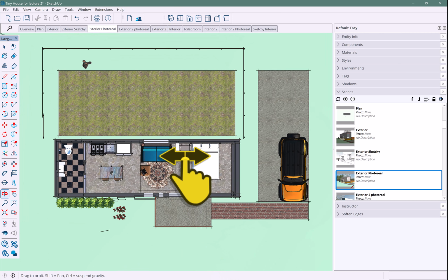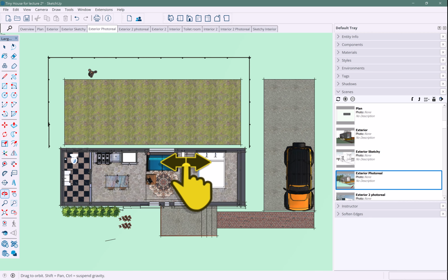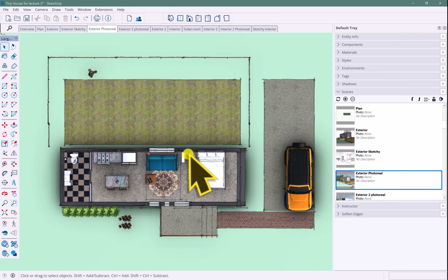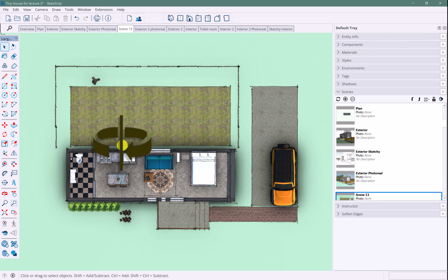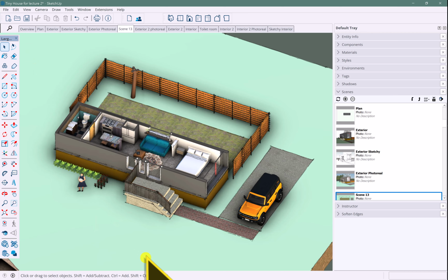So now, once we come into this view, once you flatten it, some of the ambient occlusion and other features aren't nearly as dramatic, but you can see that it makes a pretty decent combination floor plan and site plan. So don't forget, add a scene, and here you go. And you'll want to rename these because now we really are going to have a lot of different scenes. To produce the elevation, let's do the south elevation, you put in another section plane.